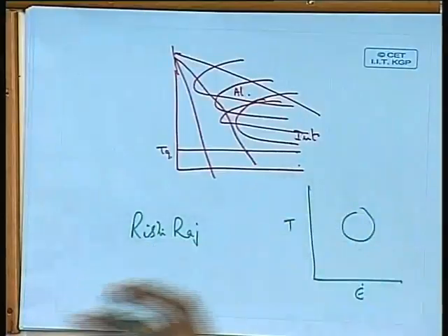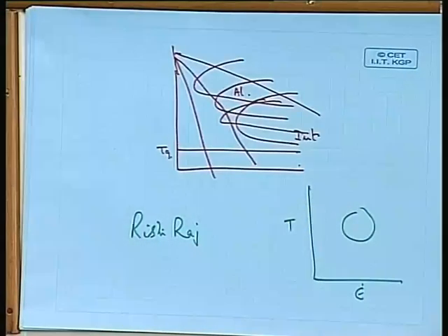So he has done a lot of work on various alloys: titanium based alloys, super alloys, aluminum based alloys, aluminum lithium alloys. In all these alloys people have worked and identified what kind of domain this is. It is very important when you want to commercially make alloys with various shapes, you need to identify this temperature and time, particularly when you are developing newer alloys such as nickel based super alloys. Unless you identify this domain, it becomes very difficult to process it over a very large amount of deformation.